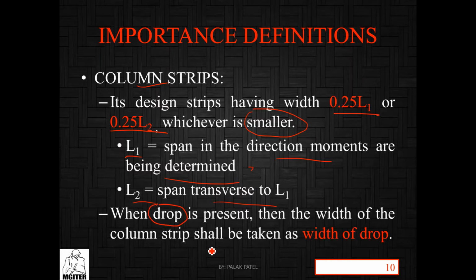How? When a drop is present, the width of the column strip shall be taken as the width of the drop. Means column strip and drop are both interconnected.